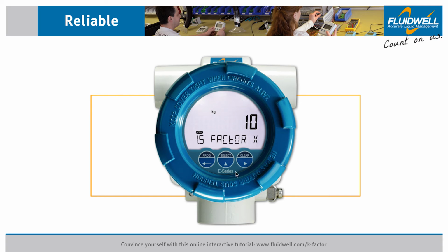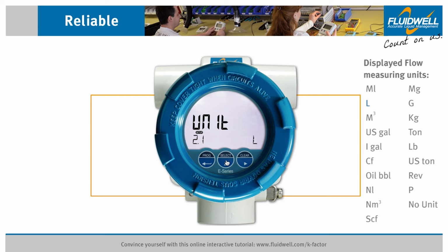Use Clear to navigate to Menu 2 Flow Rate. In this menu, you can set the display settings for the flow rate. Press Select to go to Menu 2.1 Unit. Press Prog to change this setting. We select US gallon and press Prog to store this setting. The displayed measuring unit for flow rate is now set to US gallon.